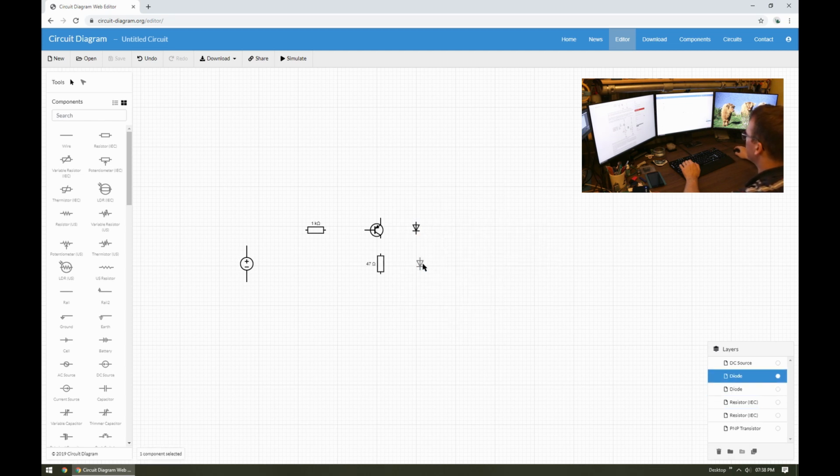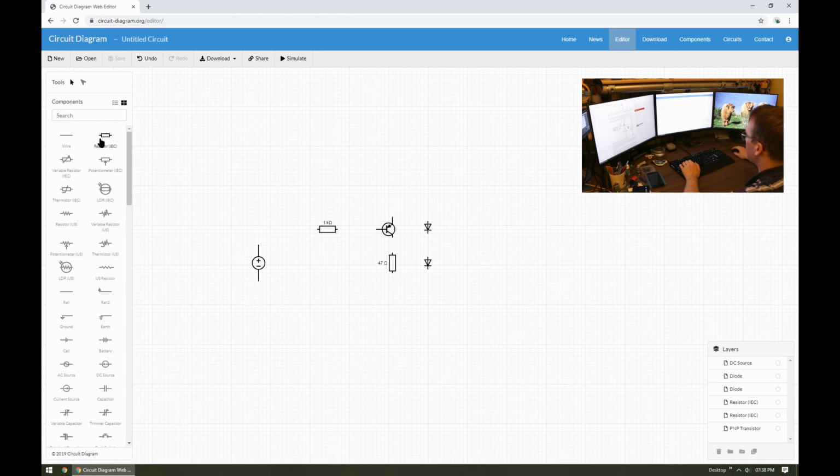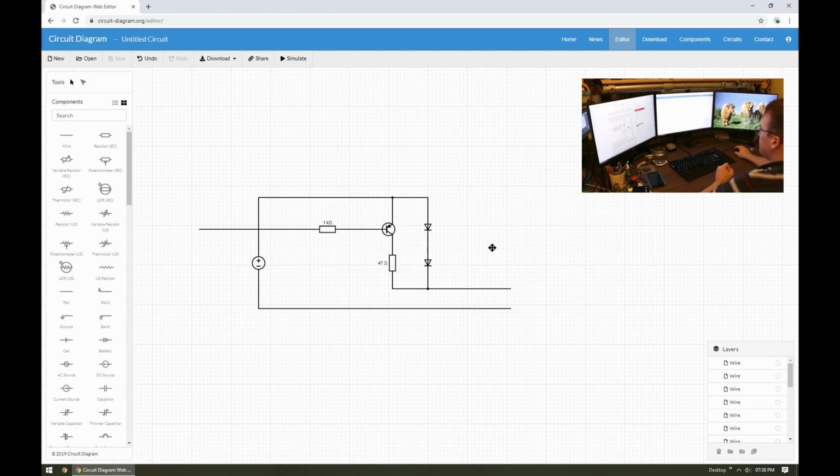These two signal diodes will provide us with the voltage drop we need. The LED chain will be connected between these 2 points, and the micro will have influence over this line to control the transistor. The transistor will pull the LED chain supply rail up to our 3.3 volt rail, and these two diodes will provide an approximately 0.7 volt drop each, so a 1.4 volt drop between the both of them. That will give us the high-high and the high-low supply voltage.